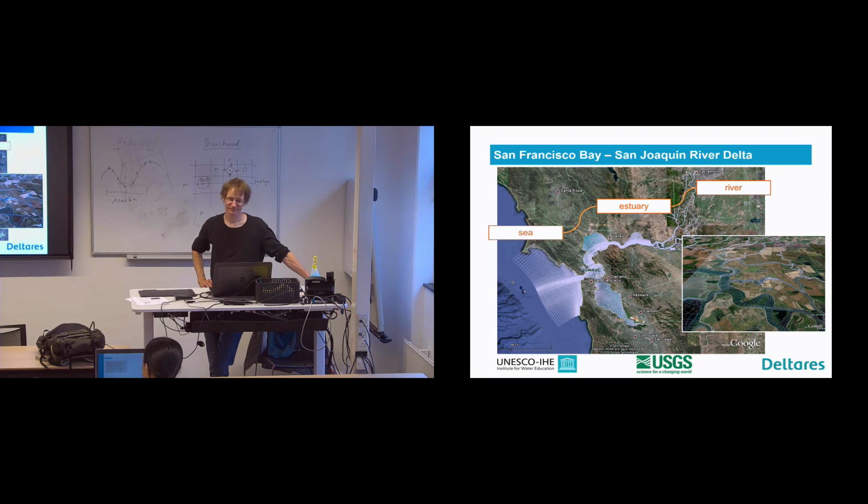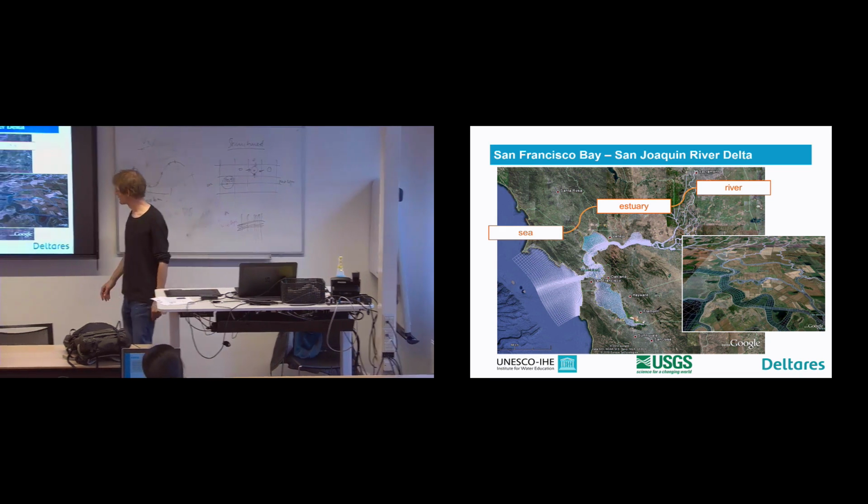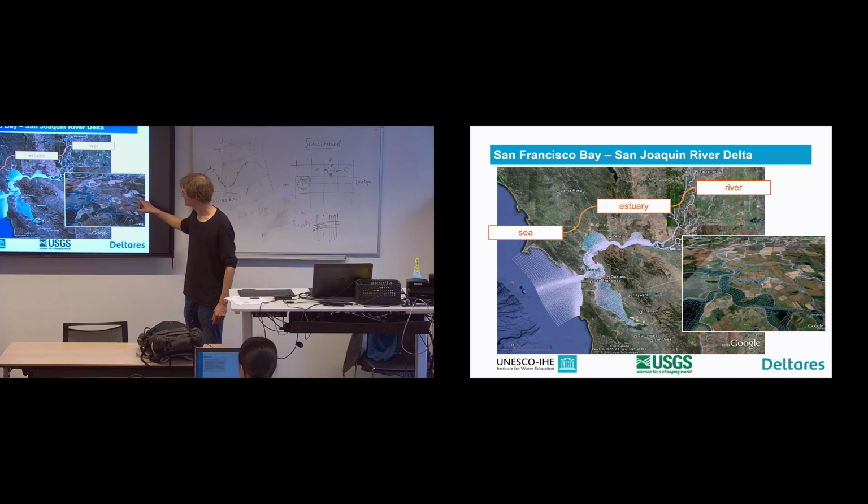Well, the problem here is of course the delta area, where you have all these networks connecting to each other, and if you want to make a Delft3D grid on that it is basically impossible. Oh, we did it once for Bangladesh, the Meghna. That was a lot of counting. Anyhow, so this is a brilliant example made by Mick and Ali of San Francisco Bay. So here you can see the delta with all the channels, and now all these floodplains are also filled up in the grid, I think by now, to allow for flooding of these.